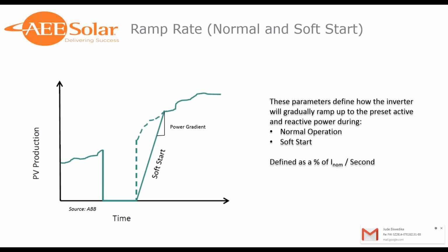So if it detects cloud cover and sees the wattage and the available wattage increasing, it's going to actively curtail that ramp up, as defined by this slope given from the utility district. Soft start occurs when an inverter requalifies to grid, which is probably what we're looking at here. So a great functionality that I'm glad was included in this standard.